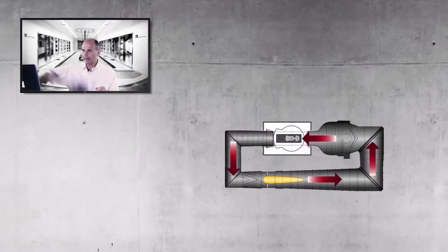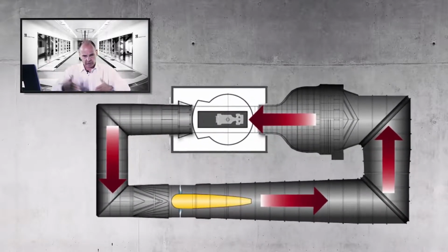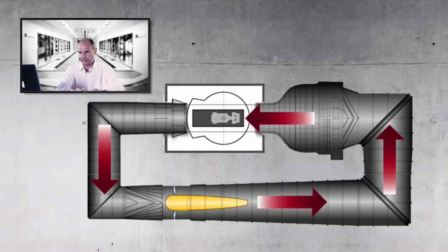And then other ways that wind tunnels have changed to suit motorsport more than the aerospace industry: when air passes over any surface, you get a boundary layer growth. So if you blow over a table, then the peak of airspeed is not going to be in contact with the table. It'll be a little distance above, because there's a certain amount of friction between the air and any stationary surface. And all the way around the airline of a wind tunnel, that boundary layer is growing. And one of the things that the contraction does is it also shrinks that boundary layer a little bit.